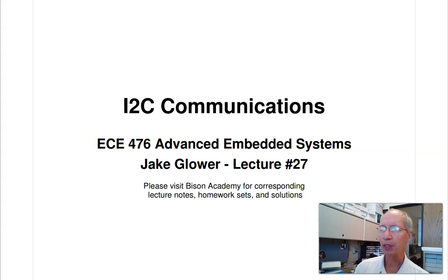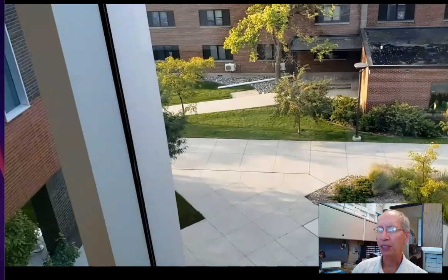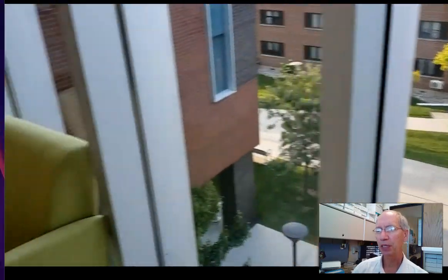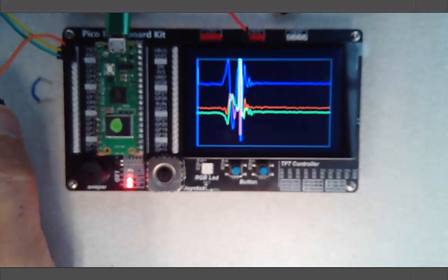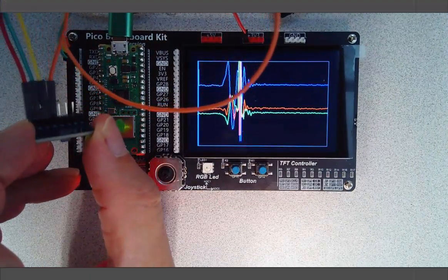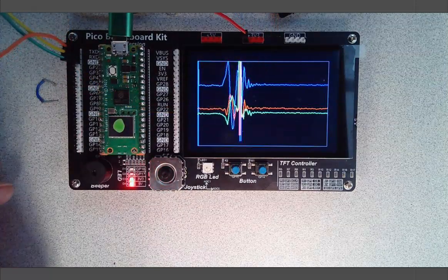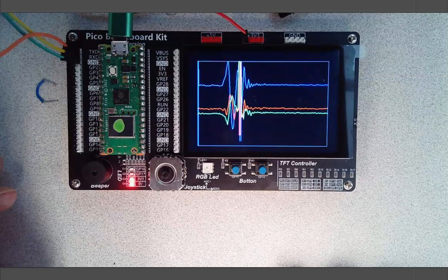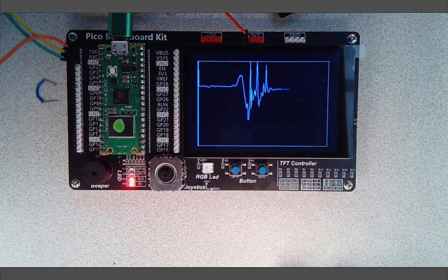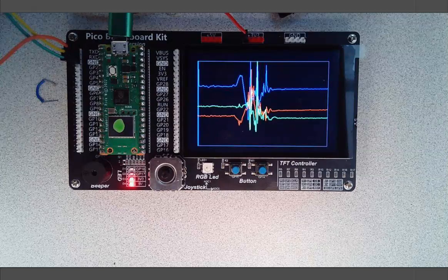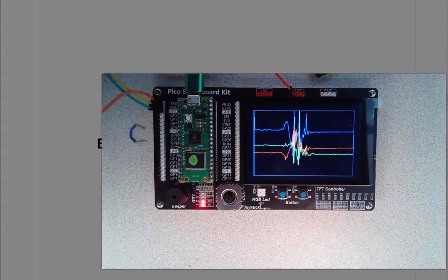Specifically, what we're going to look at is how to measure the height of a building using a BME 280 pressure sensor, or using a GY521 accelerometer to measure how high you can jump. For example, here, I'm going up the stairs of Ag Hill building, measuring the pressure drop using a pressure sensor interfacing with an I2C interface. Or here I have a GY521 accelerometer connecting through an I2C interface. I can measure acceleration versus time. So when I drop it, I can see the XYZ acceleration all recorded through the I2C interface. So that's kind of where we're heading.